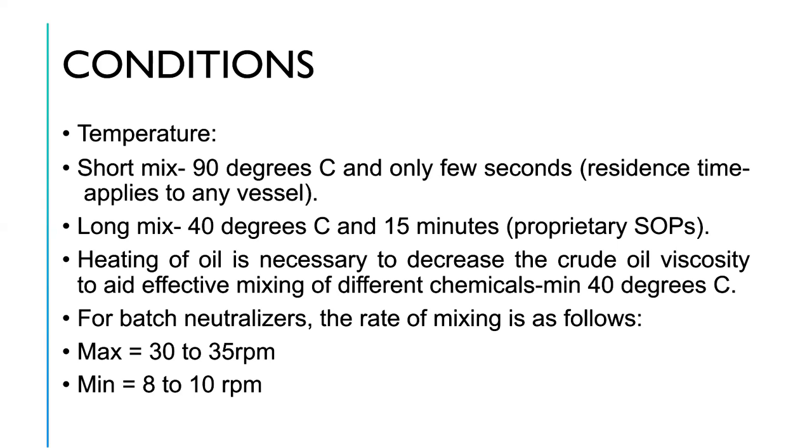So what about mixing or agitation? You need to mix at these revolutions: 30 to 35 is the maximum. Minimum is 8 to 10. So ideally use around 8 RPM, revolutions per minute, agitation.